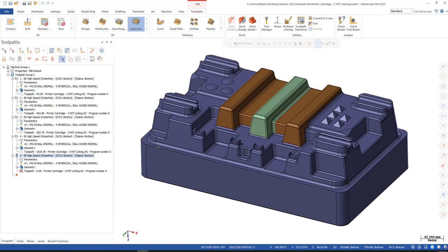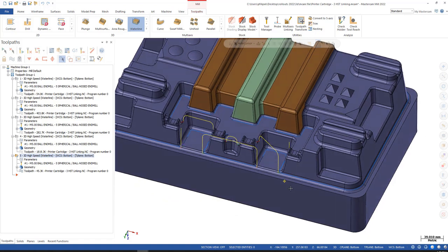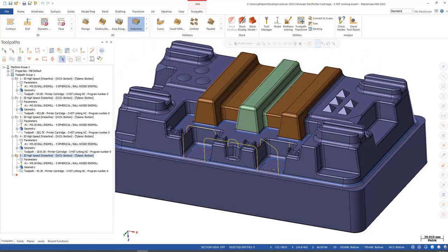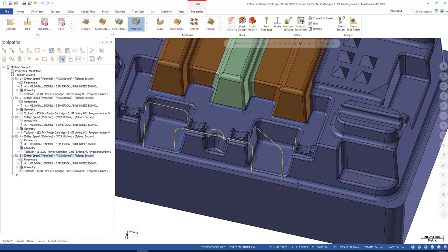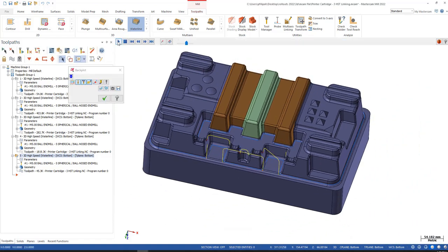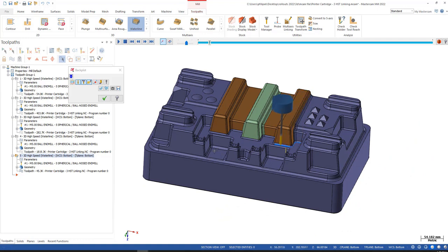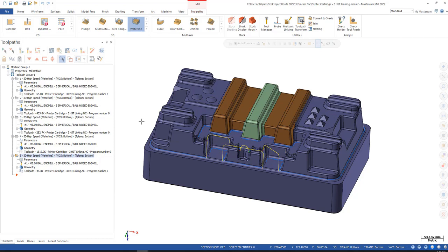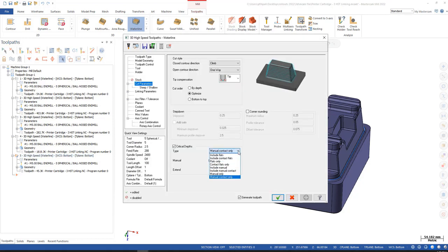Let's go ahead and regenerate this. So now you're seeing that I'm not necessarily getting a cut all the way around on all those depth cuts. It's just where it's contacting. Now this is a transition move back. So now you can see the change there a little bit is mainly just where it's contacting. So it works its way around, goes to the next one, contact, contact. So that's the difference between contact and no contact, is where it's contacting, it's going to grab those.